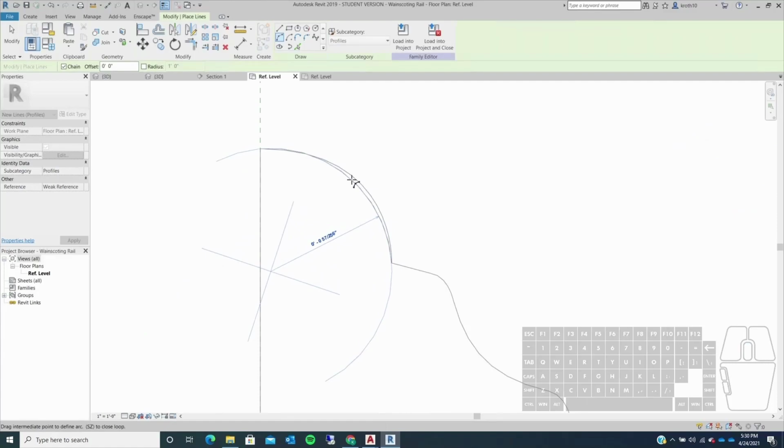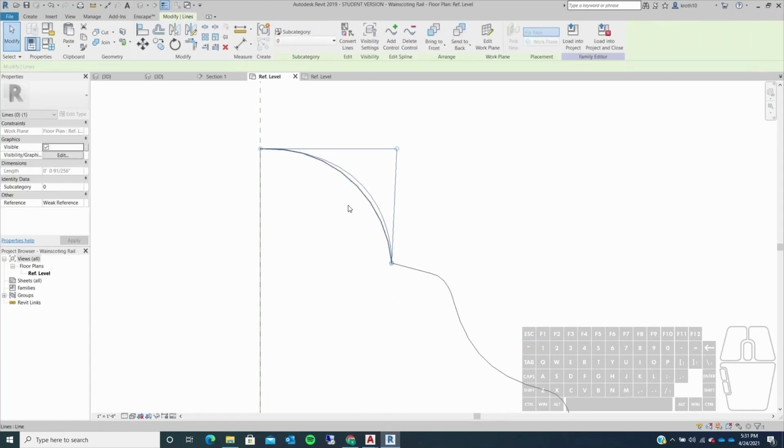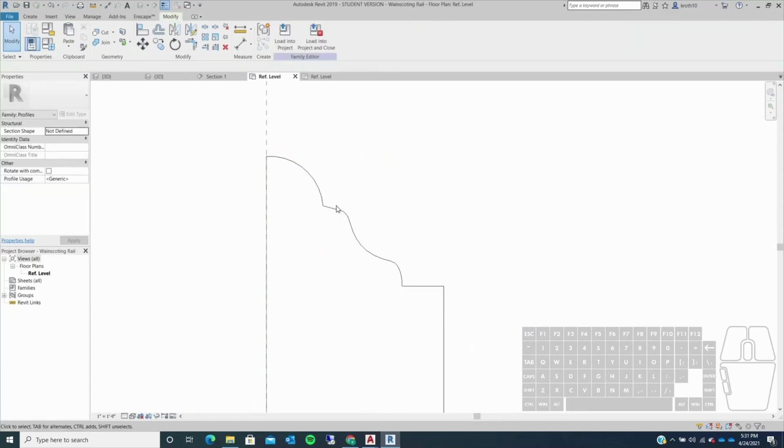I'm just going to drag this until it is roughly in line with this. Something like here will be good, because if you go too far, this starts to curve upward a little bit too much. So maybe something in here where this is a little bit more tangent is good. Then we can delete out this weird original line that we had. So that should fix that piece. The last piece is this right here.